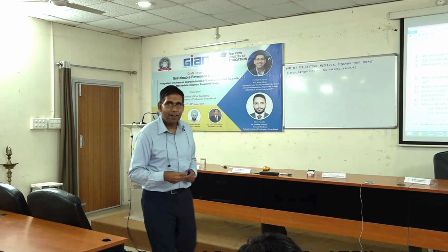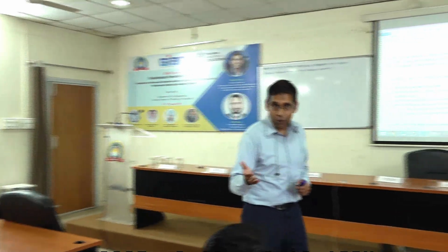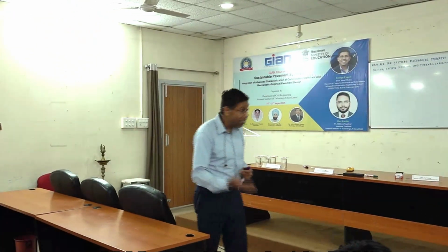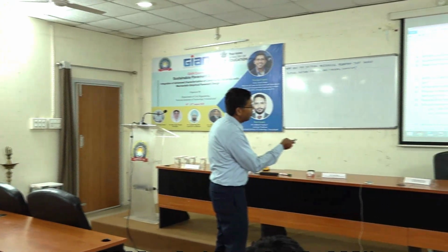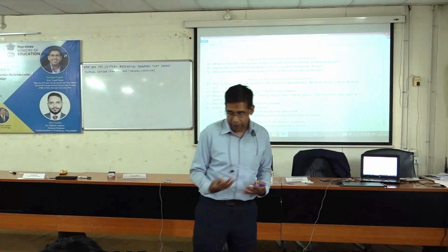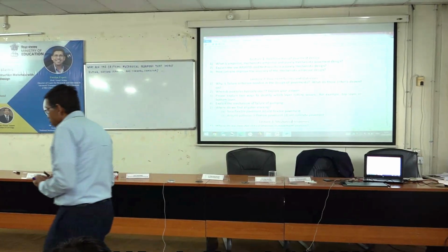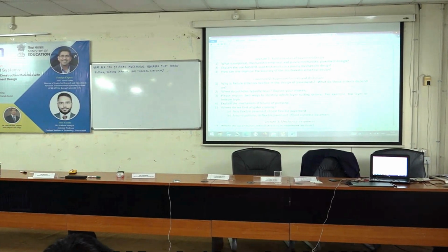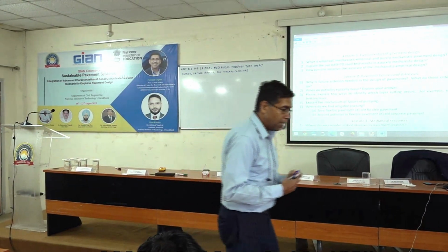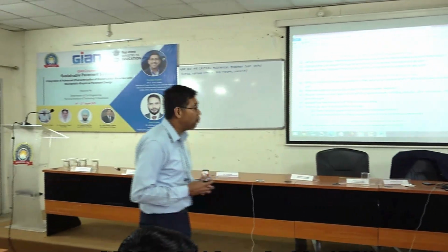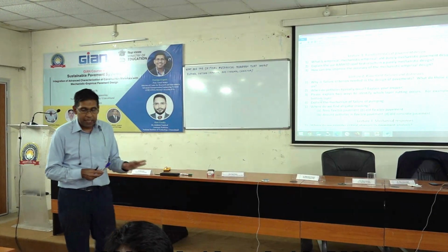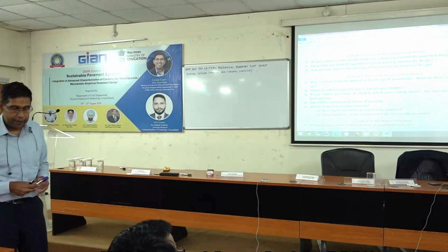Anybody online? Only to check the accuracy. So usually the role in the design is nothing, because everything you can predict accurately. So you do not need the accelerated field performance data at all for purely mechanistic design. Only if you want to check it independently. Otherwise, there is no role whatsoever. There is no need for calibration, nothing like that, because you have the ability to predict that. So it was meant for you to think through whether there is a role of field performance in a purely mechanistic design. And the only role is just to give it an independent check, but otherwise that's not needed.